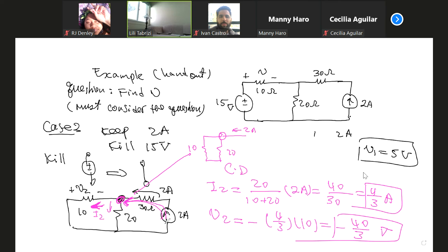Remember, any current source in series with anything, the current doesn't change. Okay, so you're completely 30 doesn't matter in order to get this equation? No, no. Thank you. Notice that any element in series with a current source is, in a way, ineffective. It doesn't affect anything. And this is one trick that they play again, EIT.